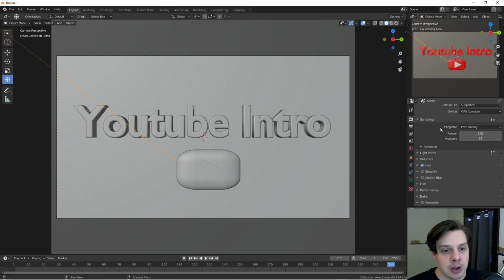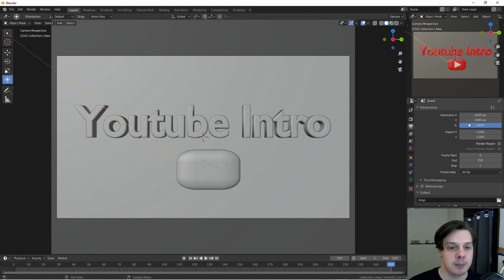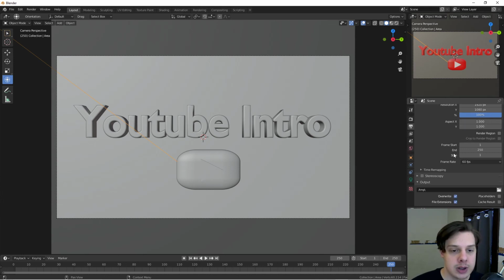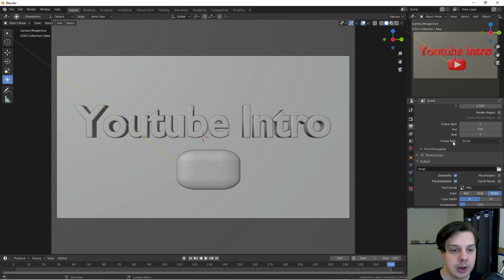So I have cycles selected, and now every step after this should be the same or nearly the same for everybody. So click the little printer icon, and make sure your resolution is what you want it at. Make sure this is dragged all the way up to 100 so you actually get that resolution. And then once that is done, you can select your frame rate,